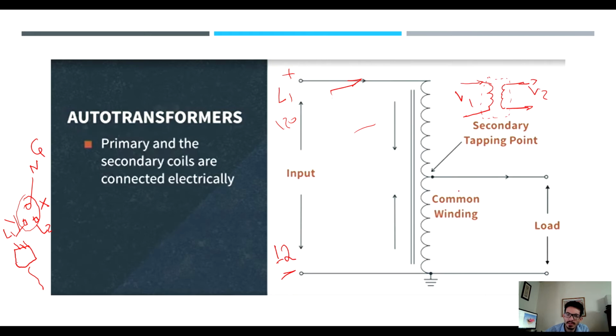So if you connect this and that, it could be 12 volts, or if you connect, say, this leg to that leg, that could be 24, etc. So you have to be careful when you use a transformer and read the drawing to see where you need to connect your motor or your system. So in this example, I'm connecting 120 volts AC and I'm getting 12 volts AC out for a motor or for a sensor, etc.